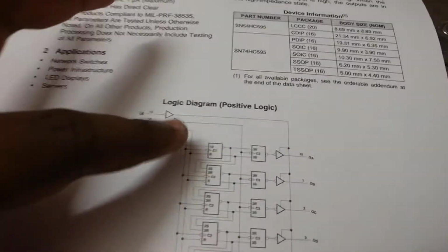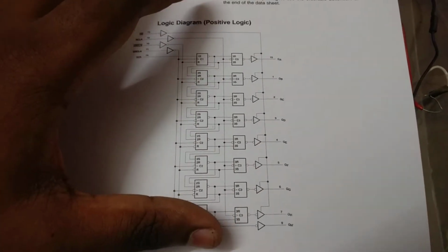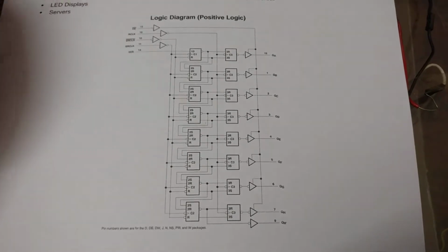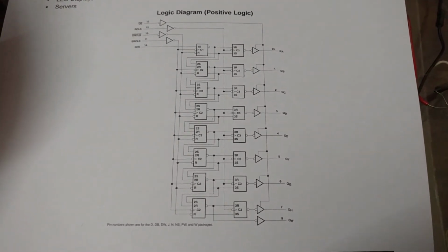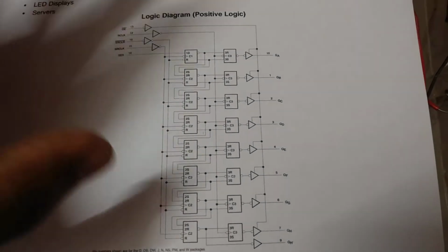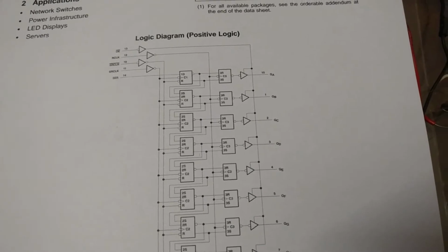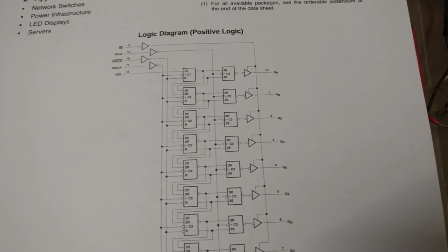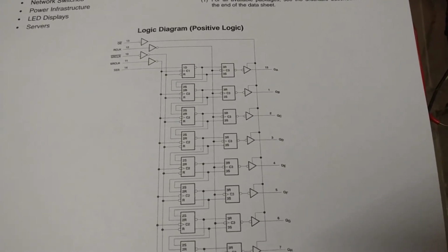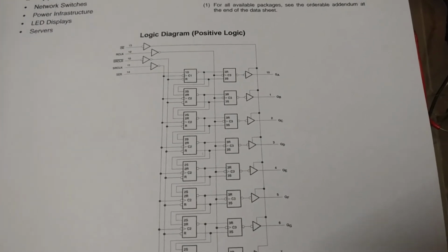So this is a flip-flop stage, and you can see there's a buffer stage, and that is here, right? This is a little bit complex. You don't have to build this much, but this always has multiple features, right? You can disable outputs and enable outputs. You can do tri-state, so it can basically disable the output as a whole, like it isn't even loading the circuit, right?